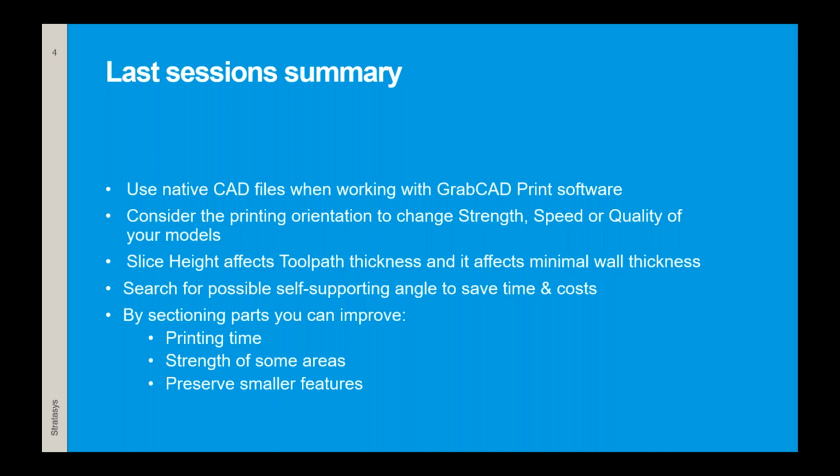So, to summarize last sessions, I showed you that using native CAD files when working with the GrabCAD Print software can really help you, and you will see today what I mean by that. But before, we can say straight that you can save an additional step in your FDM process by using CAD files and do not need to translate them to STL files.